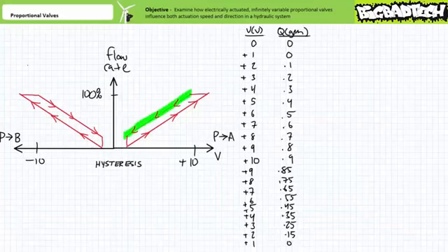When plotted on the way down, the flow rate as a function of applied voltage would look like the highlighted curve. This phenomenon is known as hysteresis and has everything to do with the magnetic friction I referred to earlier. Regular friction and oil impurities also play a part. Hysteresis is often specifically defined as the difference in control voltage necessary to yield the same flow rate on the way up as on the way down.